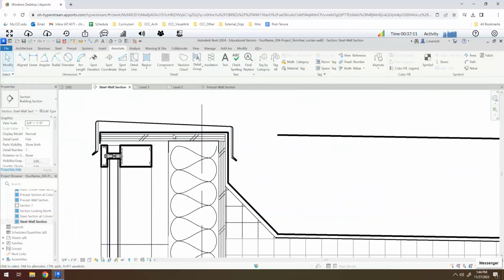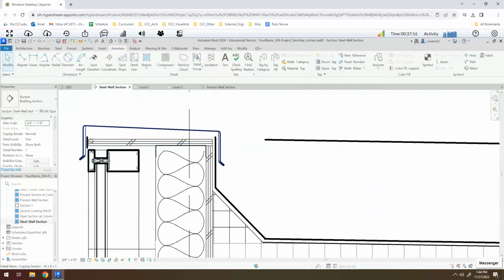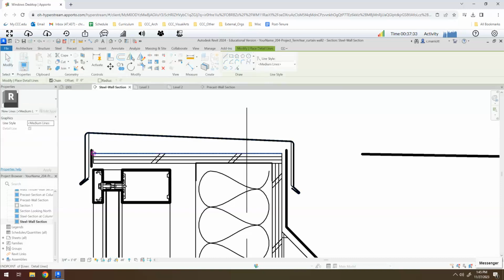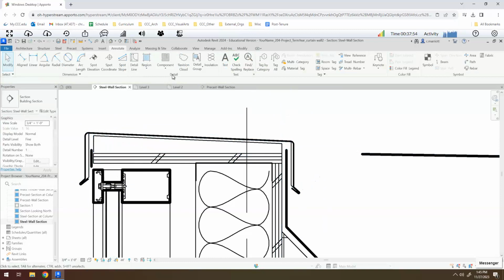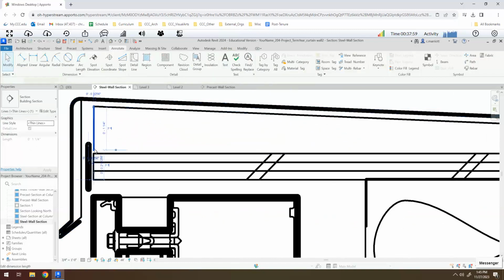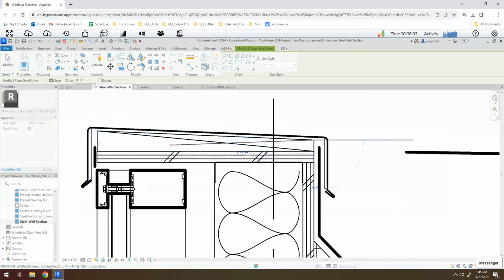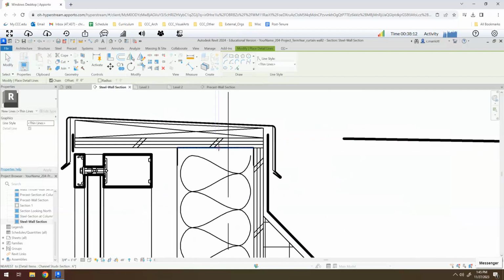Okay, now I'm going to undo this one, and I'm going to make a little change here. Now, in order to get this pitch at the right angle, sometimes we'll put in there a piece of lumber that has an angle to it. So I'm going to draw something that sort of approximates that. These should be drawn with light, thin lines. Here, go up 0.75 inches about, come up a little higher, so it's just underneath there, and then bring it down. And often what's used to indicate a piece of lumber like I just described would be an X across, as if you were drawing a wood frame sort of member.